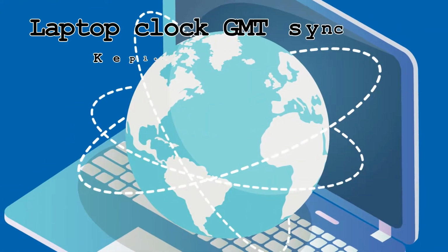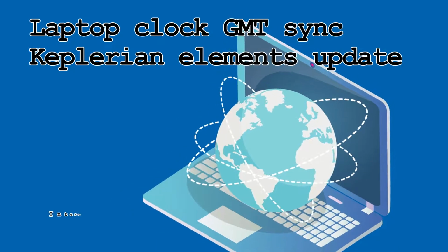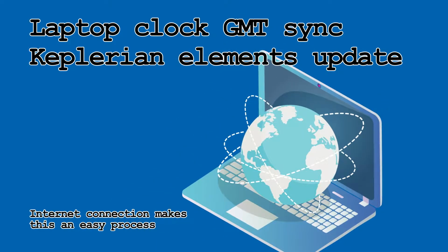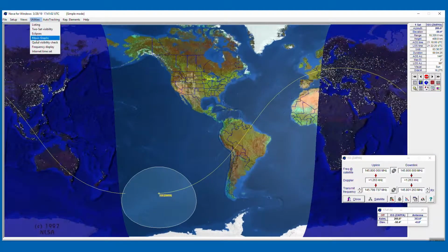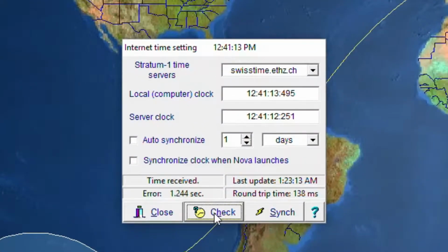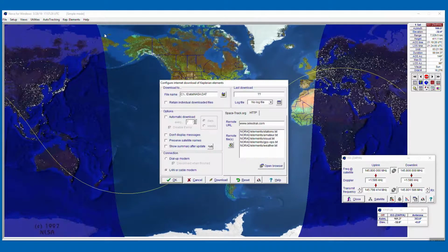Next, in order to be sure the laptop clock is accurate and to obtain the most recent Keplerian elements, it's an easy process if the laptop is connected to the internet. There's a utility to check the current time and synchronize if necessary. To update the Keplerian elements, click on the Kep Elements menu, select Internet Update, and select Configure Download.